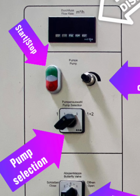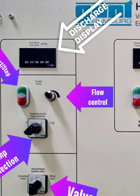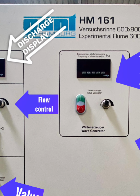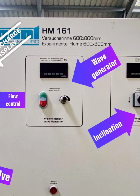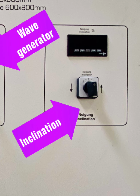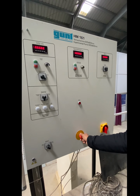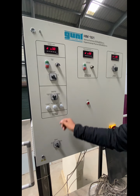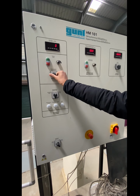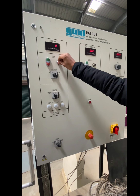And we have start and stop buttons, and we have a flow controller to control the flow rate for increasing or decreasing the flow rate, and this discharge display will show you the discharge, and this is for the wave generator, and for tilting the flume either in upstream or downstream we use this option. First we need to turn on the main switch, pull out the emergency stop, check for local remote and check for the valve, and it's open, it's fine, so we'll select pump 1 and we'll decrease the flow rate for starting.